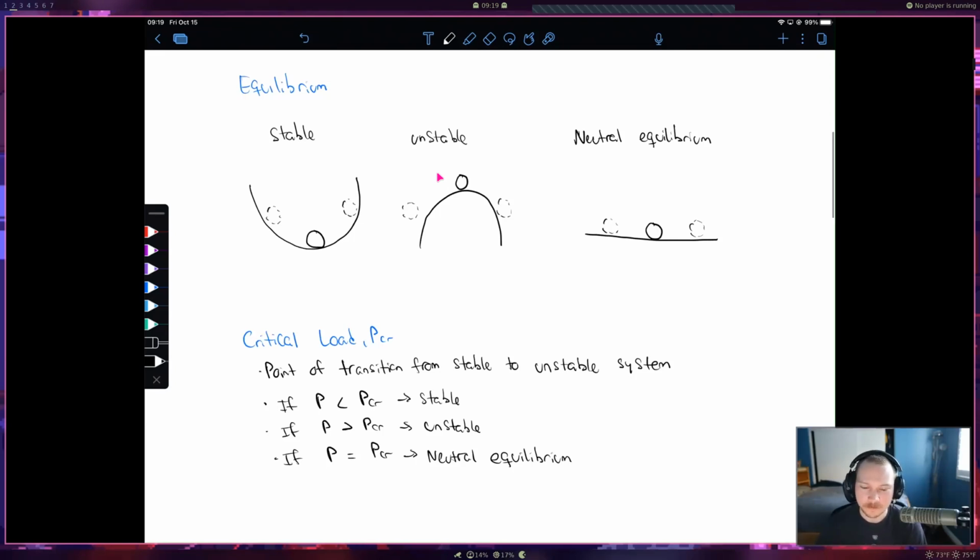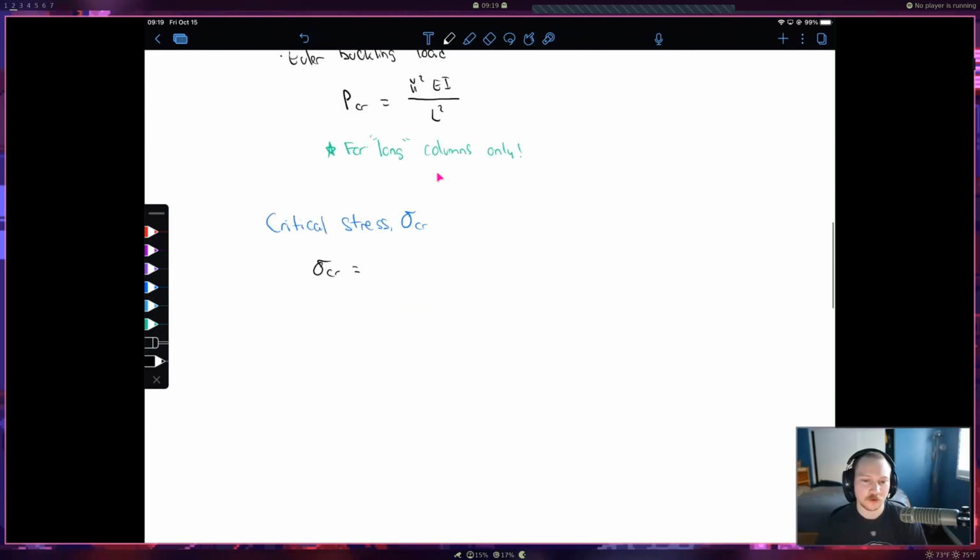Okay, you got it? Alright, so the critical stress, again, we're going to take our load divided by the cross-sectional area, and then we get our stress. So before, I think I said we're using the critical load in the graph. I guess a little incorrect there. We're going to take the critical load and convert that to critical stress, and we're going to be graphing that.